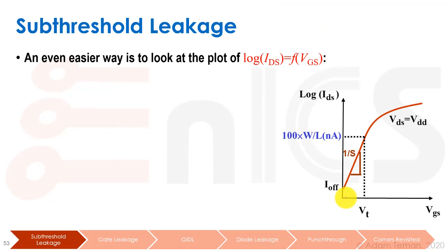And now we're going to apply a log to this IDS curve. We have our IDS curve that we know really well, this VGS to ID, which looks like this, but we can't see much in this area. So we're going to apply a log to this y-axis, and then our exponents turn into linear areas, and we get a curve that looks kind of like this.